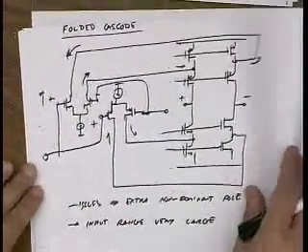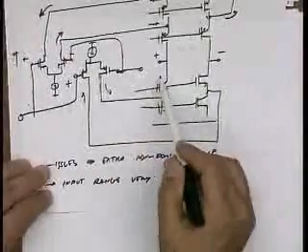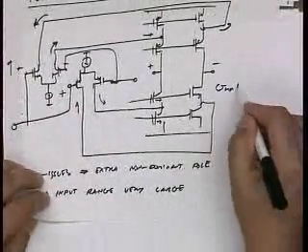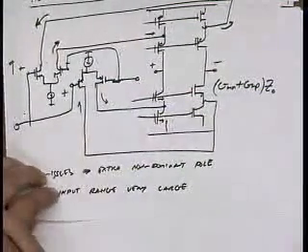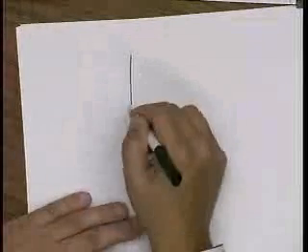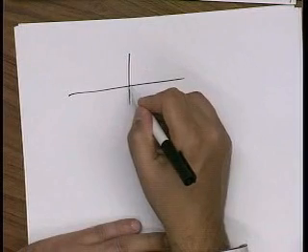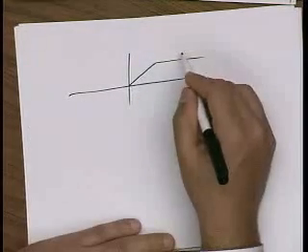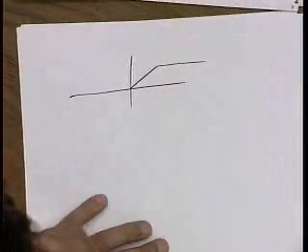Of course, one of the problems is that the gm will drop, right? Because I have 2 parallel paths, the gms are adding. So my total gain is gmN plus gmP times Z, right? So if I just had one stage, on the positive side, I hit my limit because I saturate out my current source.